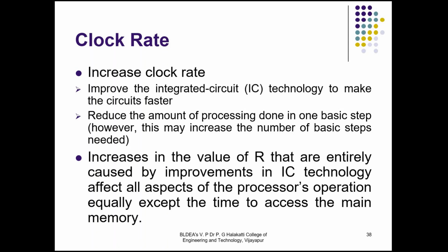The other way is to reduce the amount of processing done in one basic step. However, this may increase the number of basic steps needed. Increases in the value of R that are entirely caused by improvements in integrated circuit technology will affect all aspects of the processor's operation equally, except the time to access the main memory.